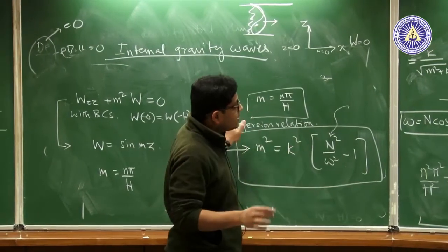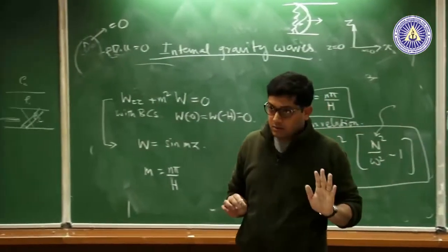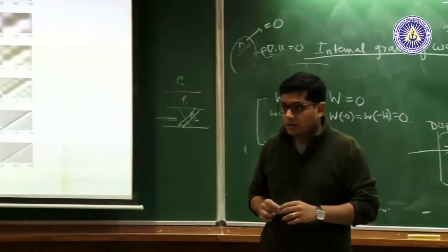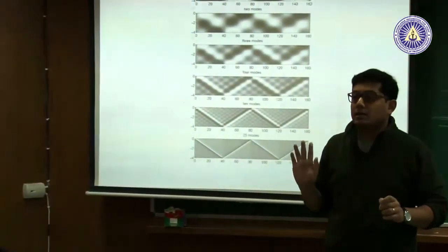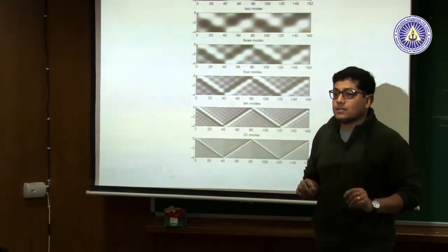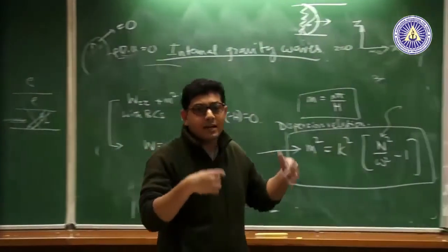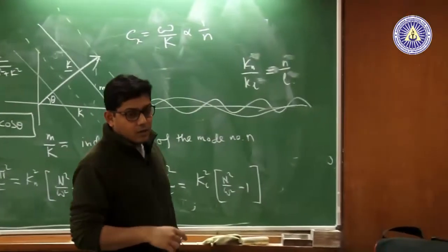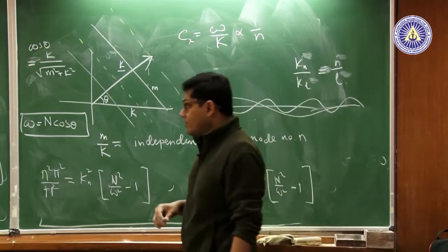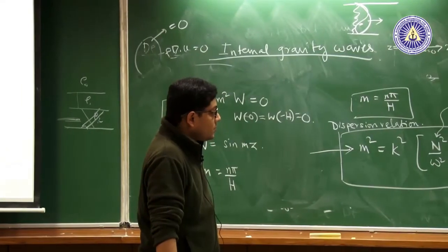In other words, if omega is fixed, your direction of propagation is determined. It is not like you have some other wave that is going to change its angle. All waves are going to propagate at a certain angle. All waves have the same frequency, because you are assuming that you are exciting them at the same frequency. The problem was not solved as a forced problem, it was solved as a free vibration problem. Yes. In the end you are connecting it to a forced vibration problem. Yes, yes.